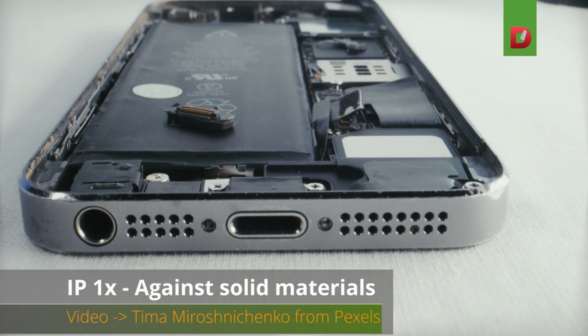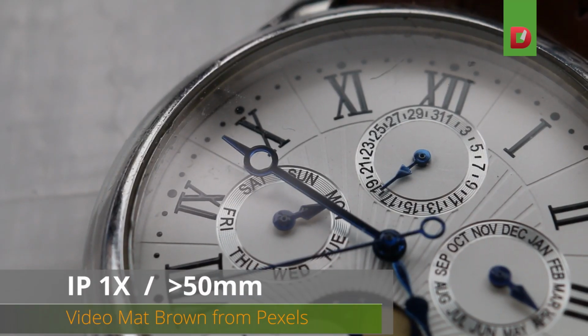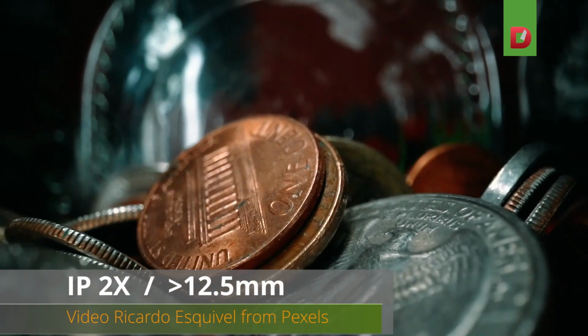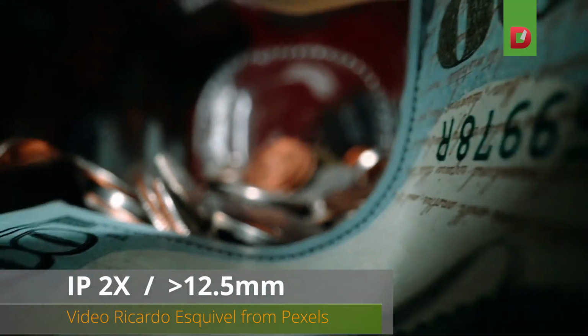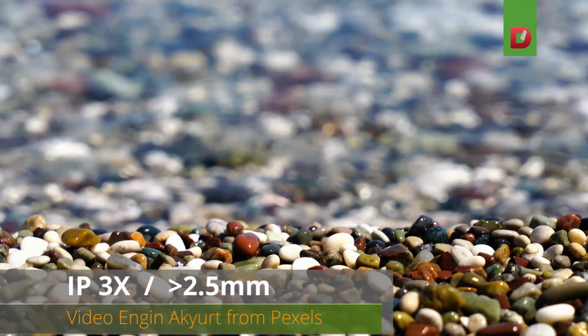Let me tell you exactly what the first number after IP means. Number 1 is protection against dangerous solid parts of size 50 mm or larger. Number 2 is protection against dangerous solid parts that are 12.5 mm or larger. Number 3 is protection against dangerous solid parts that are 2.5 mm or larger.